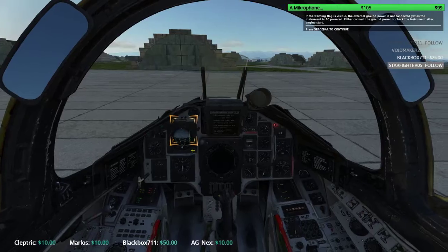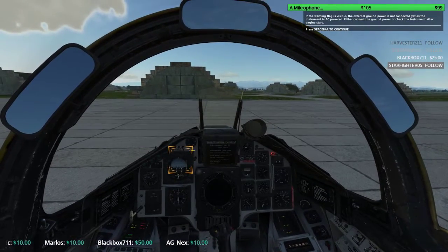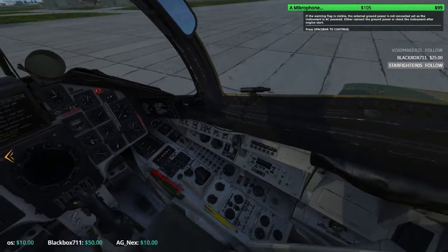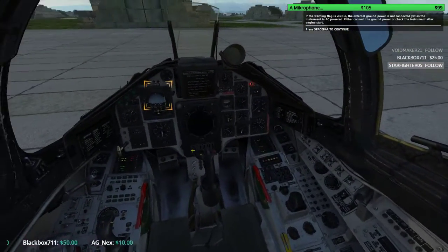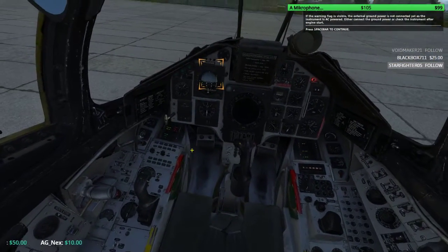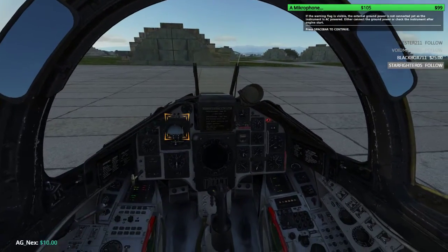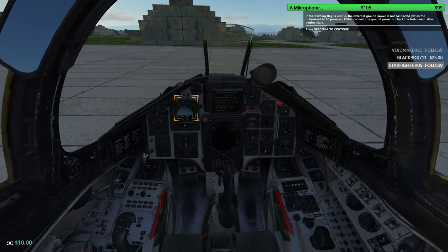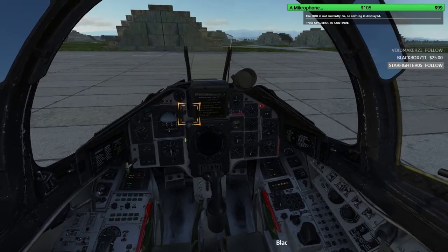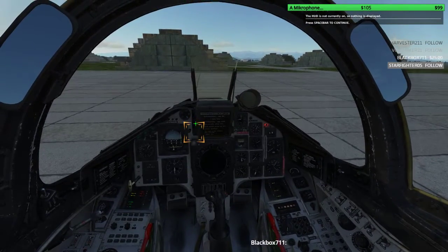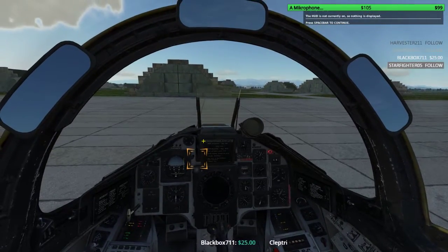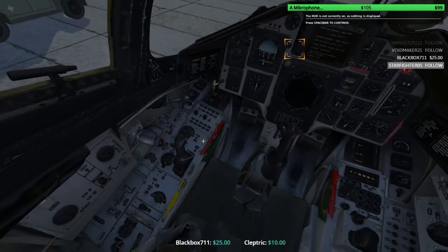Check that the main attitude director indicator, or ADI, is properly aligned and the red warning flag is not displayed. If the warning flag is visible, the external ground power is not connected yet as the instrument is AC powered. Either connect the ground power or check the instrument after engines. Set the HUD reflector glass to the lower position so that the takeoff symbology can be properly displayed. The HUD is not currently on, so nothing is displayed.